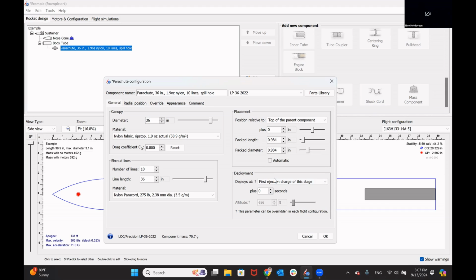We wrap it around the parachute, and it keeps the parachute sort of tied up in a bundle until the altimeter senses that it passes through a certain altitude on the way down. And then it opens, and then the parachute is able to open. And so we can program that to be different levels above the ground. But what we'll do is we'll set it to a specific altitude during descent, and we'll set that to 300 feet. That should be more than enough for us.